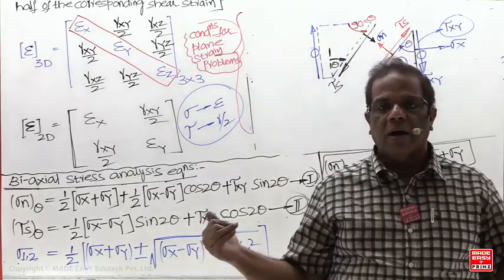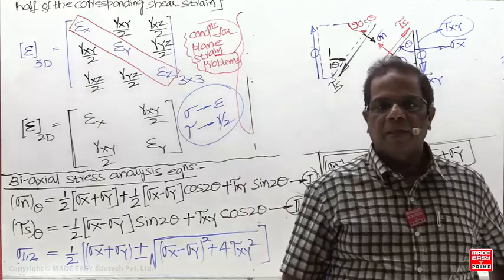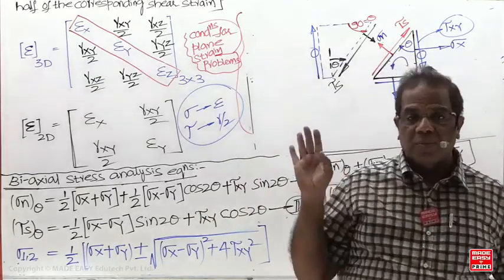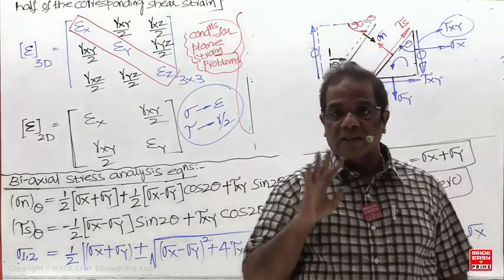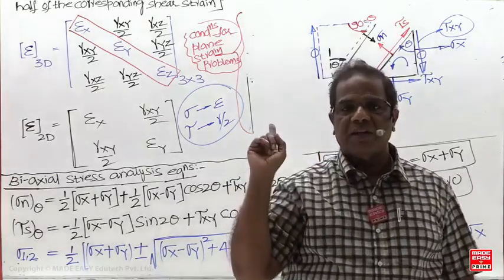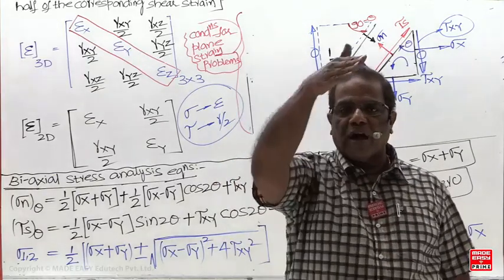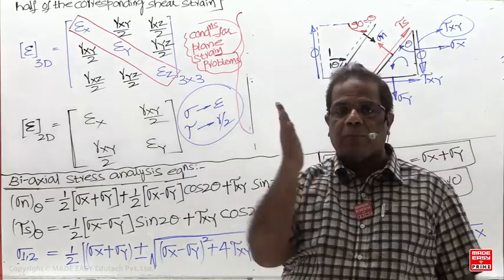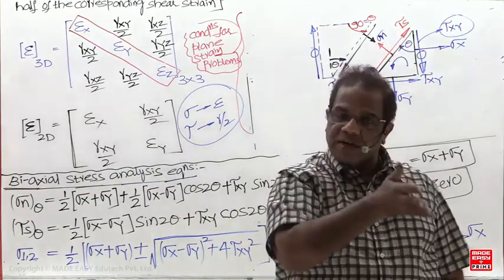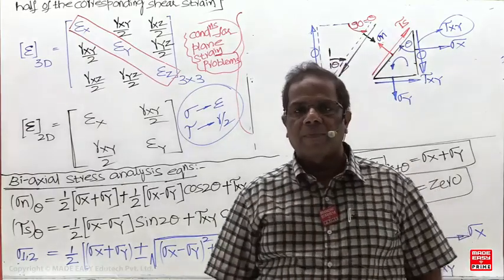But here, we don't know the loading condition, that's why you assume it. In the uniaxial case, I did not assume it. You saw that we derived that equation for an axial load on an oblique plane. If you resolve it, the normal component is upward and the shear component is upward, then the resisting shear force is downward. That's why the shear stress is downward.